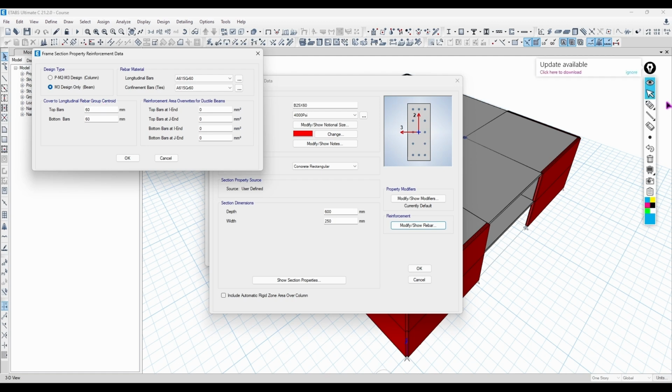Now, on here we're going to have to explain something real quick, right? So let's just get back on the screen. Now let me draw, okay, something like this. This is our cross section, right? And my steel, let's just get a kind of smaller one. Okay, so this is my rebar, 1, 2, 3, 4, and I'm just going to say 5. And then I have my tie, which is the confinement, which is going to be something like this, right? And it goes all the way up, and it just goes around, and it goes all the way down. And on this top you're going to have the hangers, which is just like, you know, from 10% to 20% of the main steel area. This is the area of the steel.